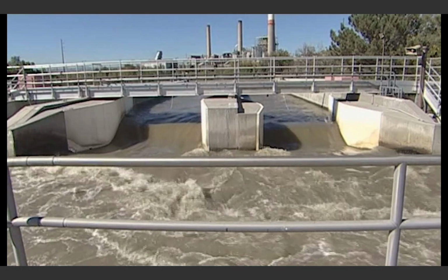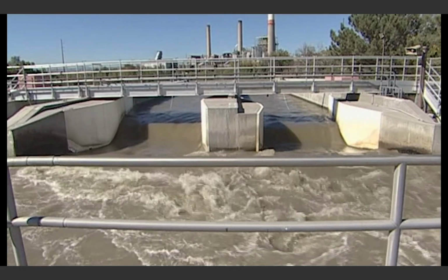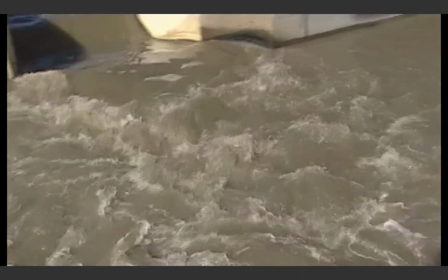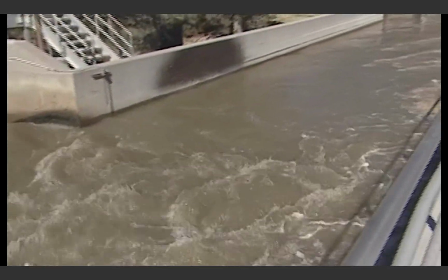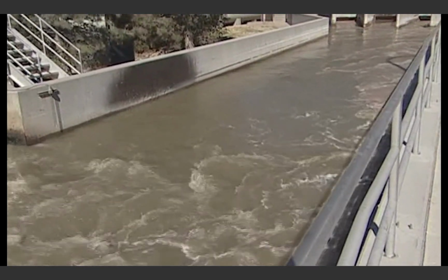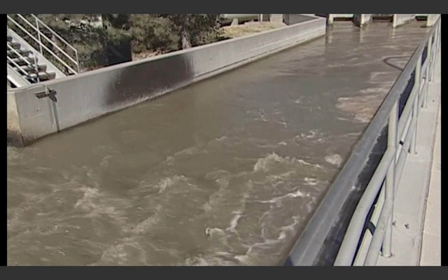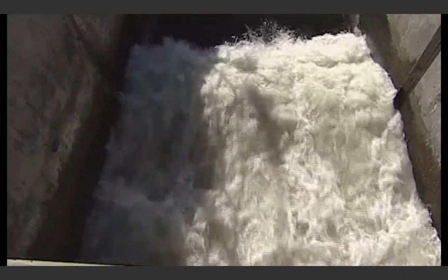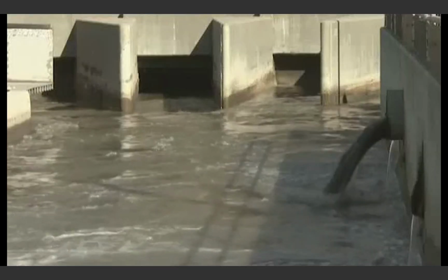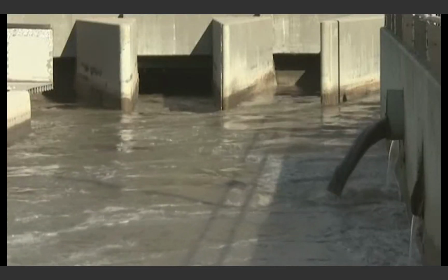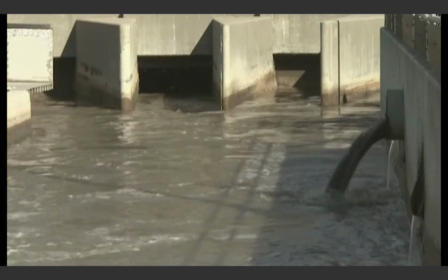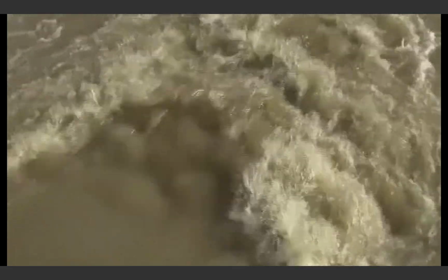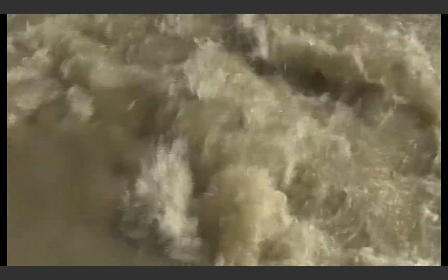Measuring the flow and loadings to the treatment plant is important for plant operations and capacity planning for both the collection system and the treatment plant. The total amount of wastewater entering the treatment plant is called the hydraulic loading or flow. Open channel flow and full pipe are two of several methods of measuring collection system flows. Plant loadings measured at the headworks of the plant give the operator a picture of organics and inorganics that the treatment process will have to remove.